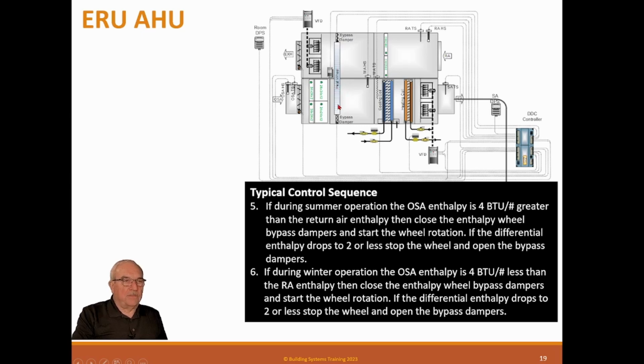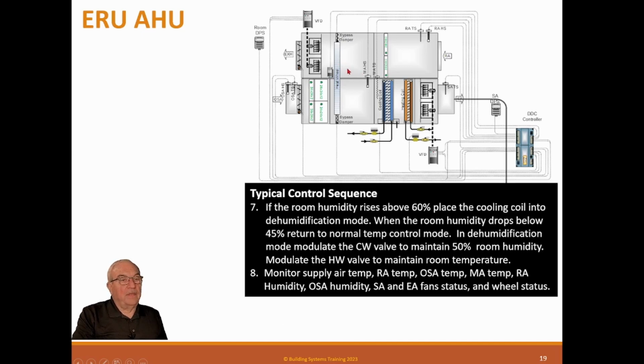The other problem is if it's an enthalpy wheel, it's got desiccant on it. If they get wet, they get totally wet, they have to be dried out. And either they have to be heated up with hot air, or else you have to take the wheel out and recuperate the desiccant. It's kind of expensive, but that can happen.